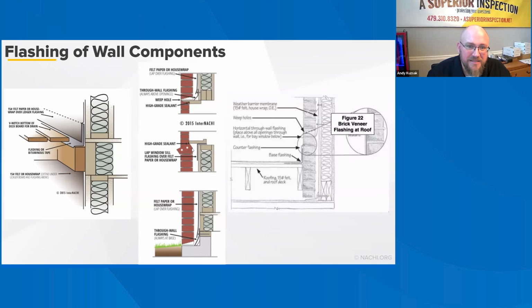When it comes to masonry contractors, they're installing this brick flat and then just applying a lot of sealant to this penetration right here. So I call out flat brick windowsills and recommend them to be redone so that the brick is pitched towards the outside.